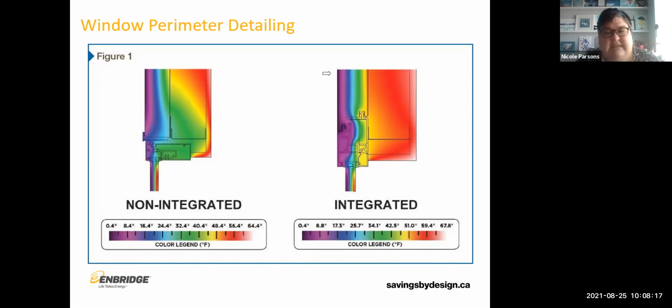So you can see that in this case where they have integrated them to avoid that 3/4 inch space of nothingness, yeah, there is a little bit of a space where the heat loss is higher, where the surface temperature has dropped a little bit here. You've got your stud, you've got the framing, everything lines up. But in general, those interior surfaces are staying significantly warmer.